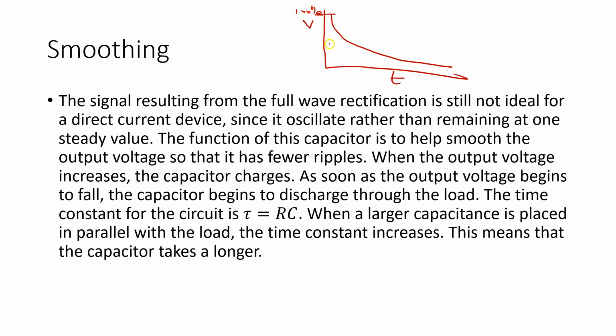If I wanted to find the time constant from the graph, I would have to look to see what amount would be 37%. Once I find 37%, the time on the graph that corresponds to that will tell me the time constant. So that's how we find the time constant using the graph. It's just when 37% of the initial amount is remaining.